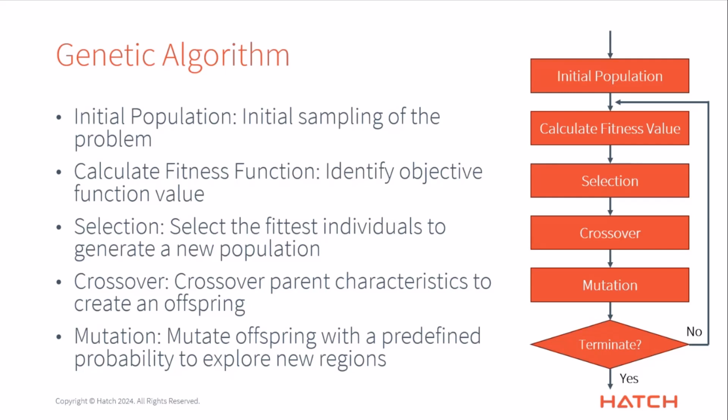So you start by defining an initial population, where that's going to get characteristics of the manipulated variables through your optimization problem. So you set your bounds for the manipulated variables, and it's going to create a population of individuals that have randomly selected values between those manipulated variable bounds. Then you'll assess the fitness of each one of those individuals. So you'll find what the objective function value is for that unique combination of manipulated variables to get a fitness value.